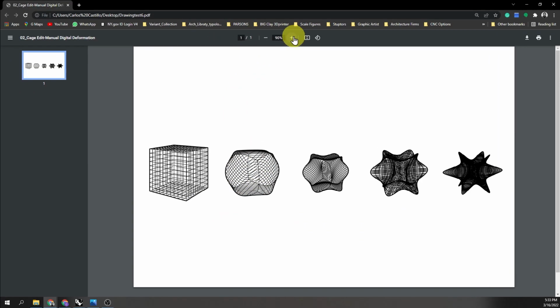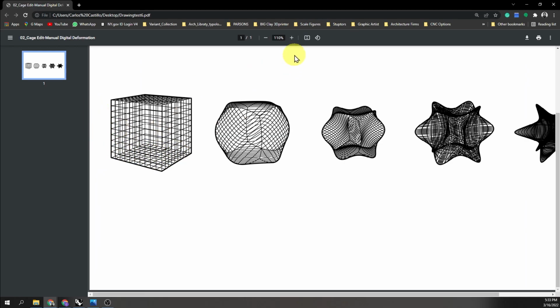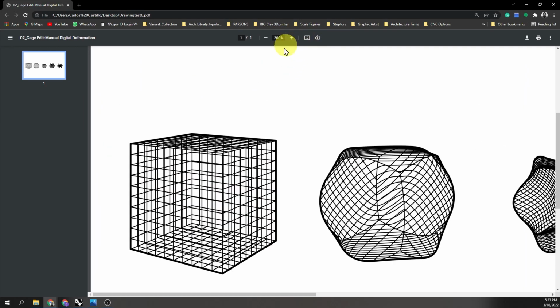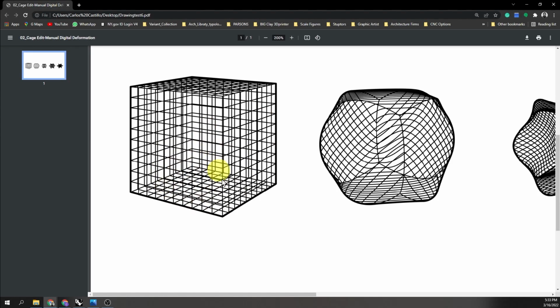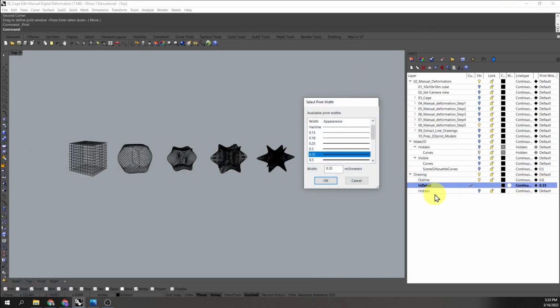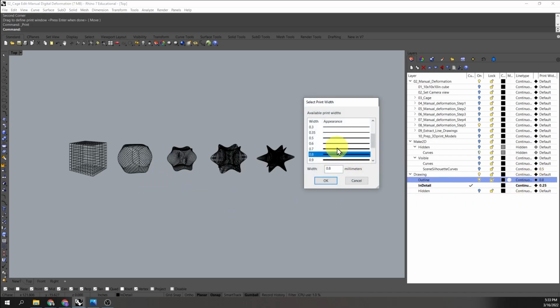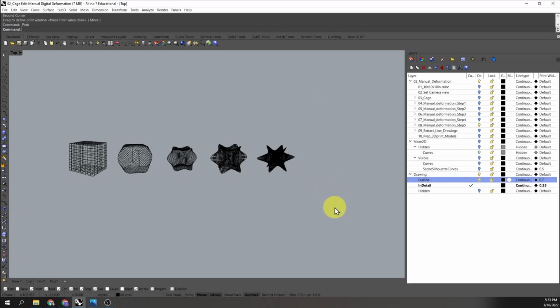As you can see, now you have both line thicknesses there. And you can play with the thicknesses of the lines. This might be a little too strong. It depends on the density of your lines, right? Let me go back here to my interior detail lines and make this a little thinner. Let's make it 0.25. And the next thing I'm going to do, I'm also going to reduce this outline to 0.7.